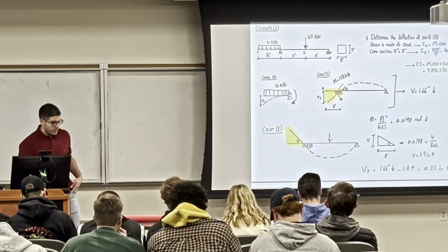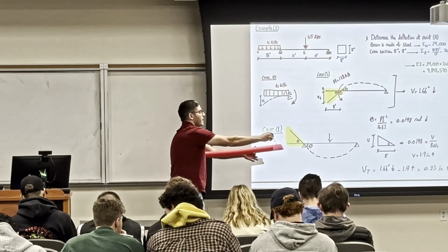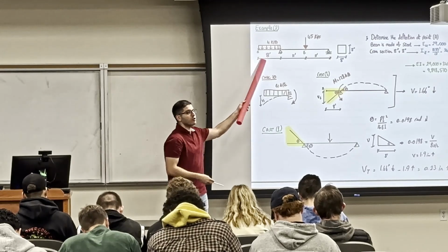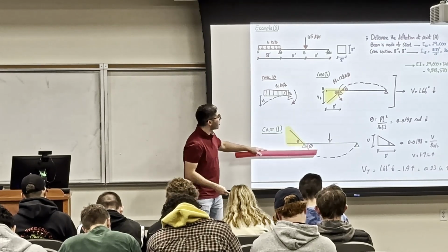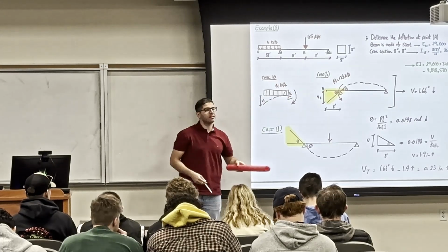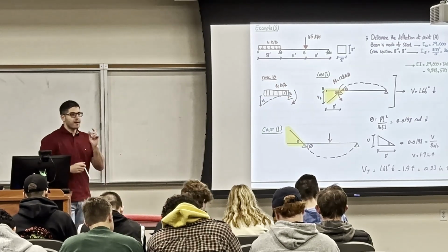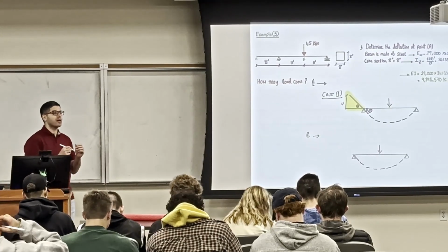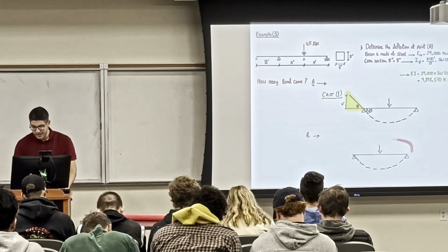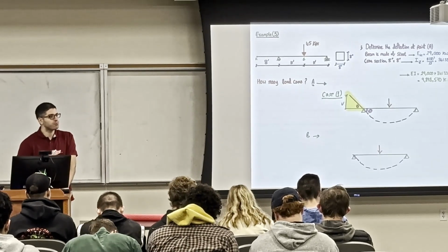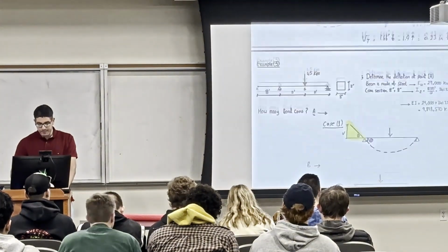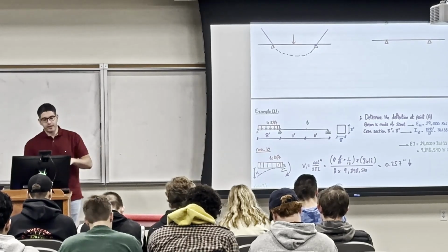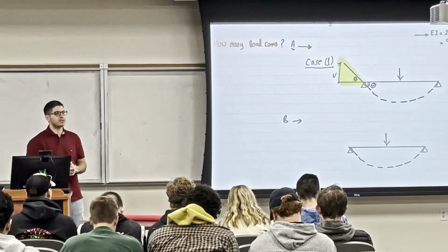In addition, when I have a beam with a cantilever, if I have a load at the end, it's gonna affect the midspan. That's why if I have a load at the cantilever, I'm gonna take case 1 and case 3 to find the deflection at the midspan, which is at point B. But the difference now, for point B here, we don't have loads on the cantilever. That's why we're just gonna take this load case, and it's good. So these 3 examples are very important so that you understand when to use the correction, when to use the effect of the cantilever, and when just to put one load case and call it good.